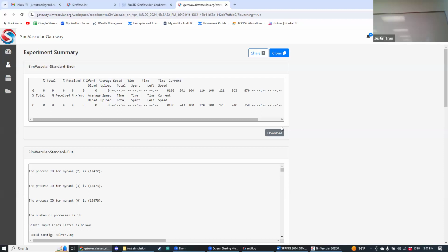What you can do is artificially smooth this vessel out. I know you tried really hard to follow that vessel as closely as you can, but you can maybe eliminate one of the segmentations here so that you have a nice smooth vessel. So we're getting away a little bit from the accuracy, but for something like this, sometimes you have to trade off. This is going to be the most challenging stuff for you guys, getting the mesh. But once you get the meshes, you'll feel better.